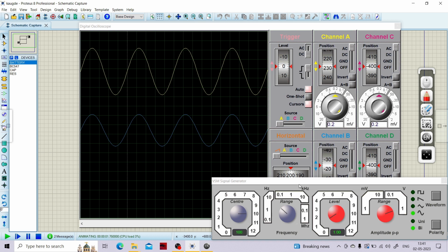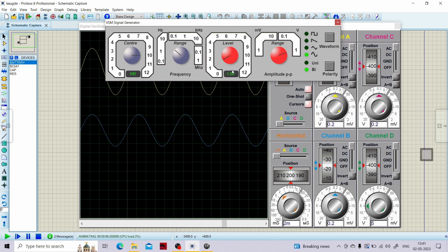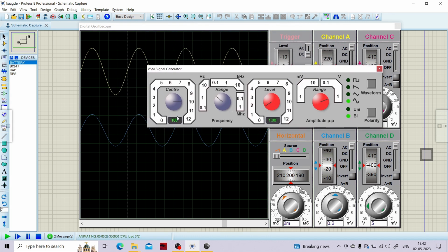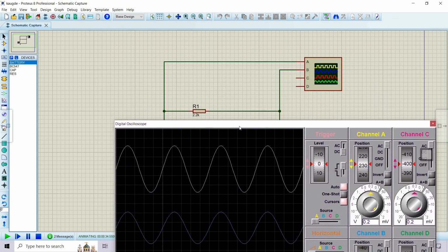All right, before coming to this part, let me show you the input signal. It is 1 volt peak to peak, as I had mentioned, and the frequency I had kept is around 100 hertz, because the frequency of an ECG or heart signal is around 70 to 100 hertz, something like that. I'm not that sure, but for this practical scenario you can take any value of frequency. That's not a big concern for us. What we need to check is the voltage that we would be getting.